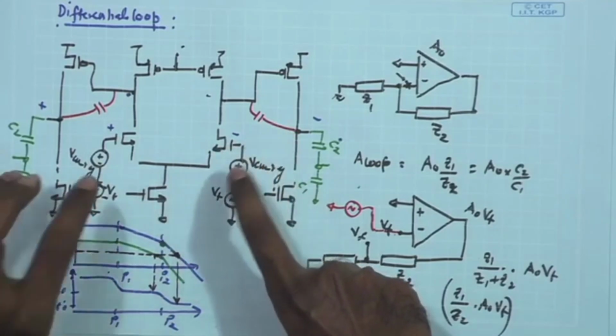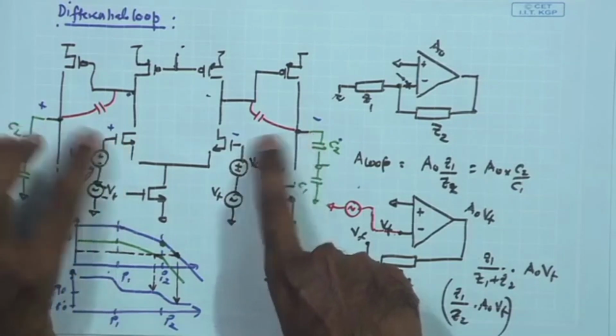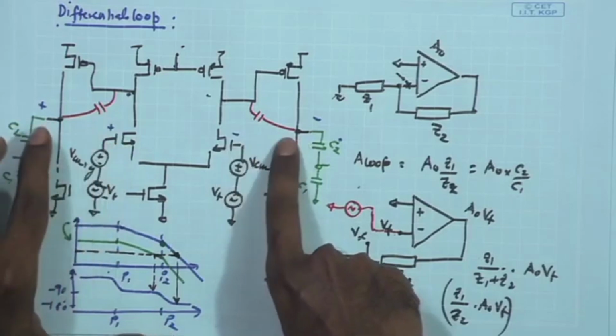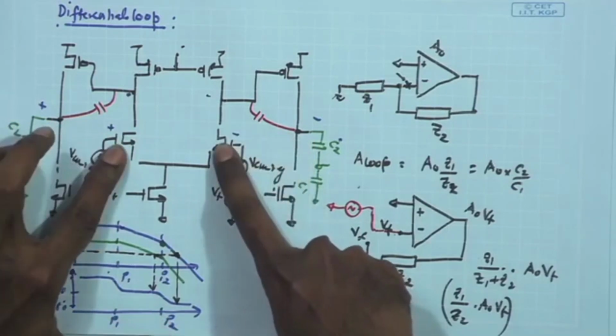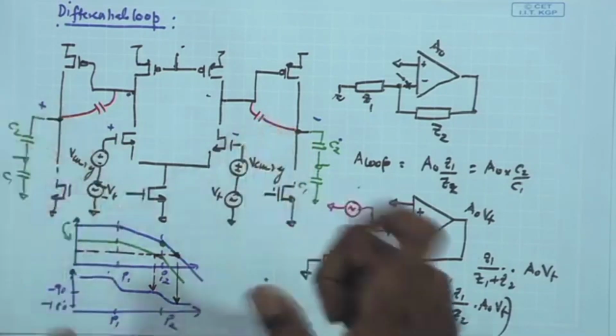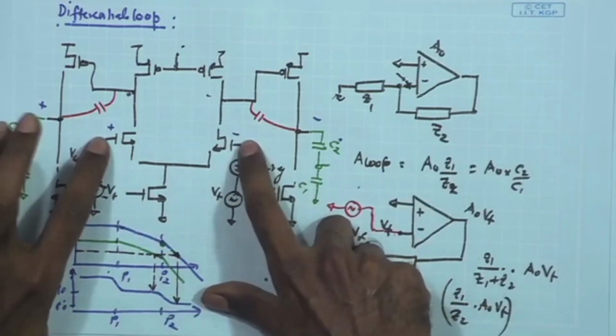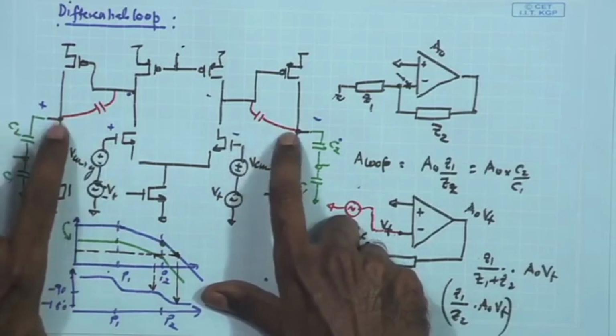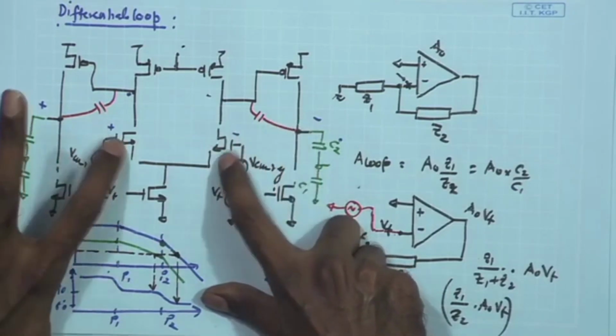In that case the RF is not playing any role anyway, so you can eliminate it altogether. Even its presence will not matter much. So, you can confirm that even if you have RF between these 2 points, that high impedance resistor that you implemented using transistors, it is not going to hurt much in the overall simulation, because it is very high impedance.